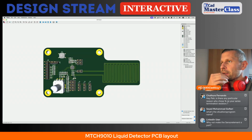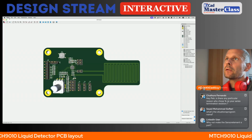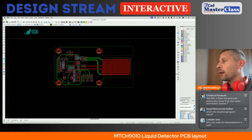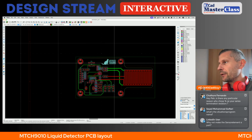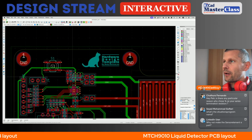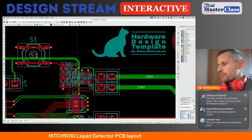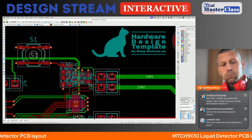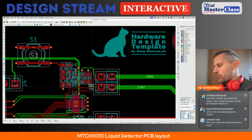Okay, so let's work on the silkscreen before we call the DRC. Why? Simply because now we should get many findings, many warnings, because the silkscreen labels are overlapping the pads, which is a manufacturing issue.